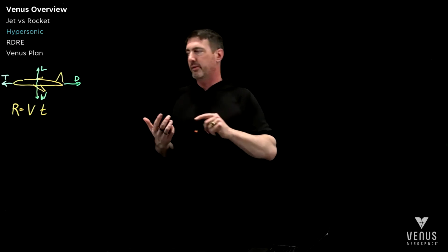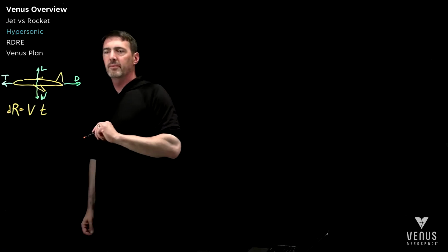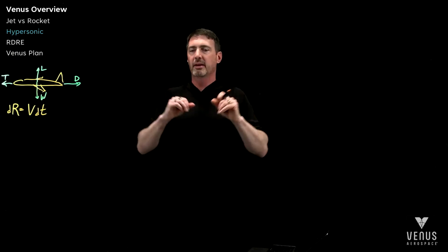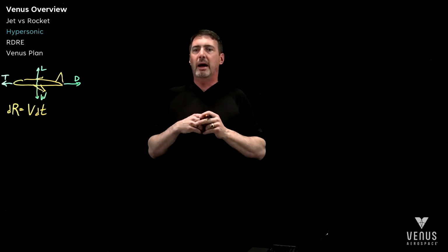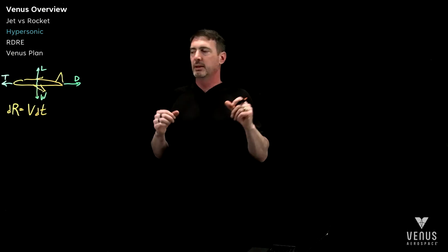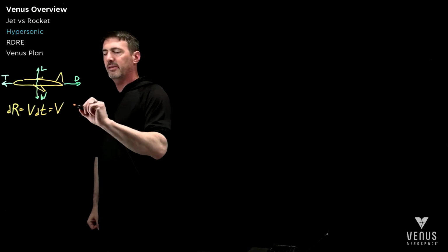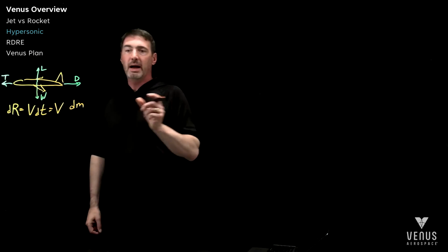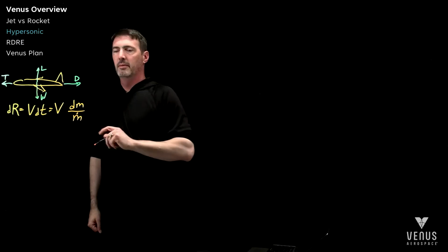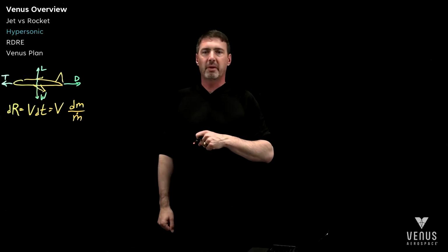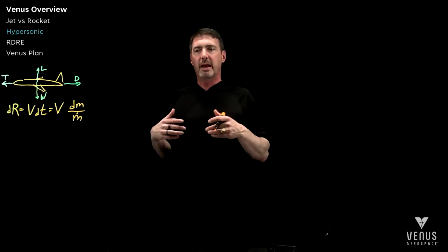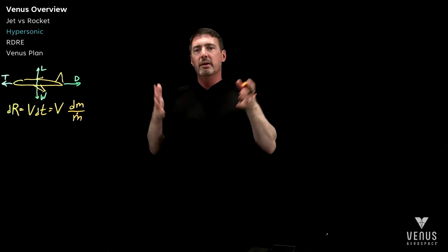And so what we need to do is talk about a little segment, given a little moment in time. So at this snapshot in time, the aircraft weighs this much, is burning this much fuel. How much little range is it getting for that little moment in time? And then we would add them all up, or integrate. And so this is a little bit easier to cast because this is now just how much mass, I burned a little bit of fuel. And then what's my fuel rate? So how much fuel, say in pounds, and then my fuel rate in pounds per second. This would give me now how much range I did in a little moment in time, a little